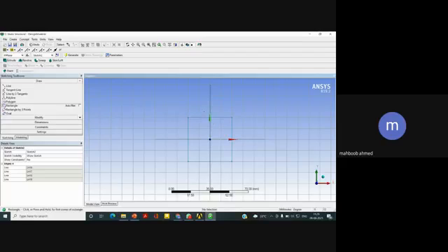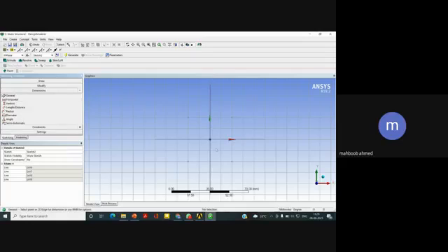I'm not going to specify the dimensions of this. If you want, you can click on this, select it, and specify the dimension. It has already taken 40 mm. I have drawn this in such a way that it has already taken 40. And the vertical line, V3, how much is it? 40 mm. It is already taken. Now I click generate and my sketch has been generated.